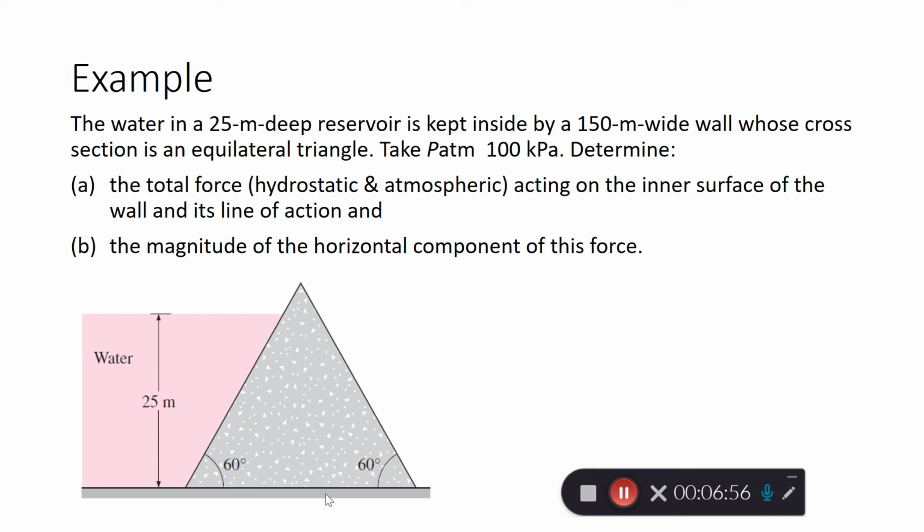This can be easily explained by the need for a thicker wall at the bottom, because of higher pressure at the bottom, so you don't want the wall to collapse at the base. If you recall from the very first picture of this chapter, there was a picture of a dam, and the dam has a thicker wall at the bottom. So this is the case. But of course, in order for the wall to be effective, it still has to be a full rectangular wall.